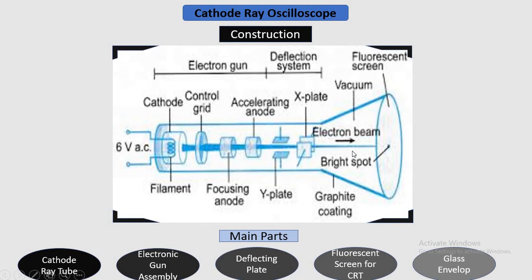The next part is the fluorescent screen of the CRT. The front of the CRT is called the face plate. It is flat for screen sizes up to about 100 mm by 100 mm. The screen of the CRT is slightly curved for larger displays. The faceplate is formed by pressing molten glass into a mold and then annealing it.